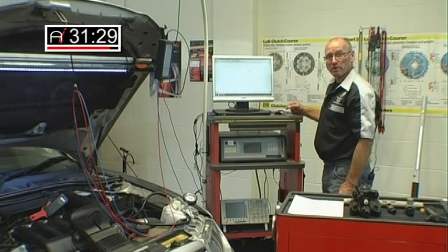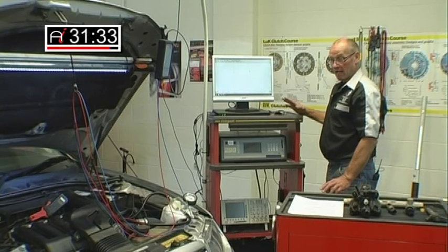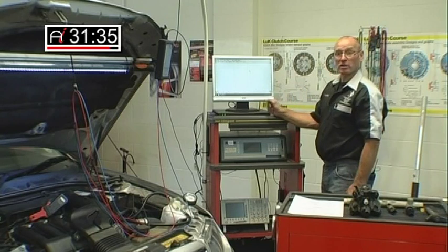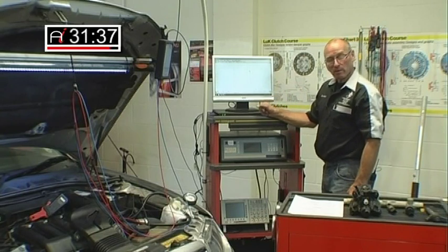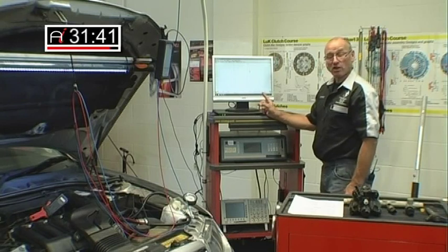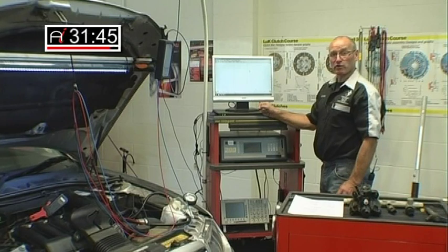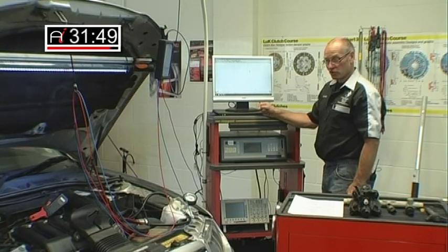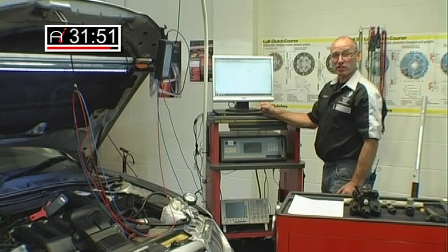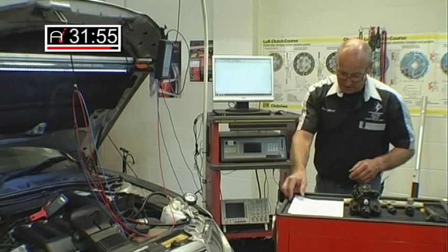There is nothing wrong with the driver circuit to this injector, and therefore I am satisfied that the coil and the ECU and the wiring and the capacitor and the ground are all good. That's on that injector. We do of course have to then test each individual injector and or wait until a failure occurs to determine if one particular injector has failed. So I'm just referring back to the DTCs.